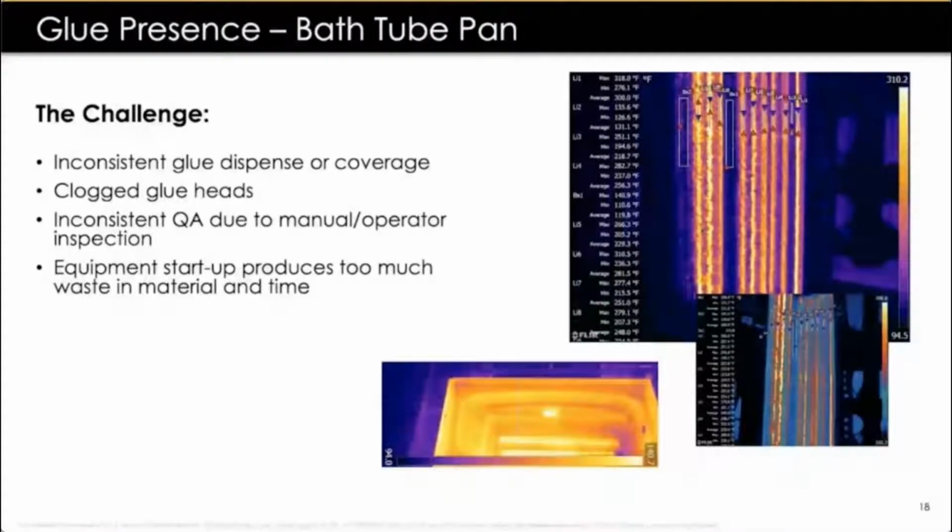So we were called in, and once this customer was educated on the value of thermal imaging, being able to see these streaks, we were able to do inline processing. In this particular process, they actually turnkeyed this. Once they saw that the head was missing the strip, they could do a lot of overlap. I know in a lot of your applications, you may not be able to go back and repair with the robot due to cycle time, or because you can't apply a second layer of adhesive. But in this application, they just asked the robot to go over and do one more pass.